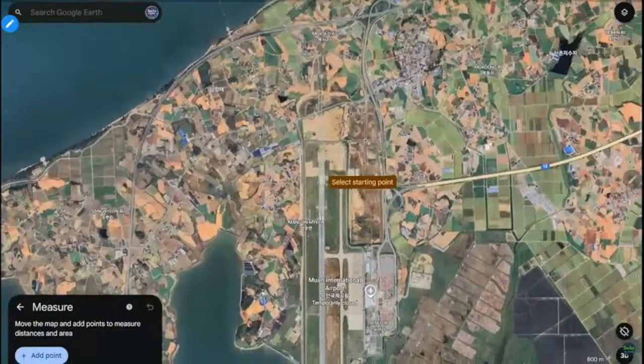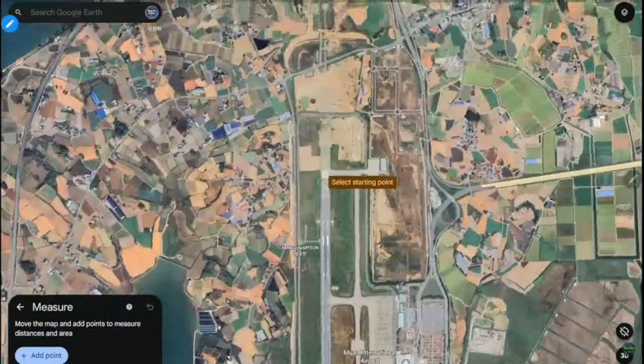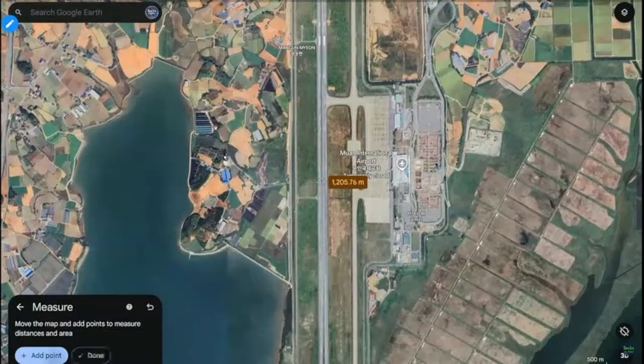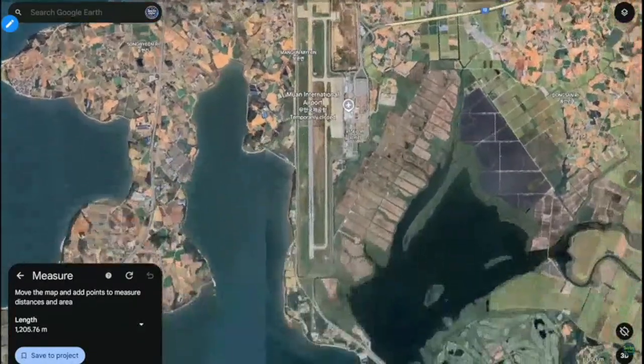But one of the things that happened is on this runway, typically, you want to land clear of the threshold and probably somewhere around here. But what actually ended up happening is if the runway measurement starts around here, it didn't touch down until about 1,200 meters, so probably around here, unfortunately. And so that means almost a third of the runway was already used up before they actually touched down.